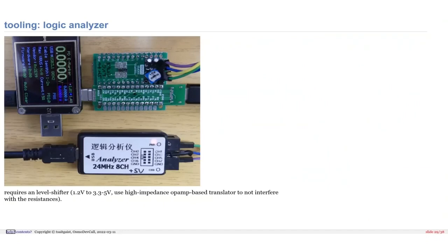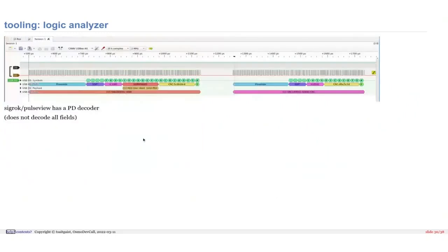This is how I actually started sniffing power delivery. It's just two small level shifters and a logic analyzer, because Sigrok, the open source tool for logic analysis, has a power delivery analyzer. And this is actually the trace of the U2 power meter, which asks the cable for this information. We can see again the preamble, which is for the training. Then we have the start of packet, SOP, and you can see SOP prime. There's one little prime thingy, which says somebody wants to talk. So either it's for the cable or it's from the cable, both things.